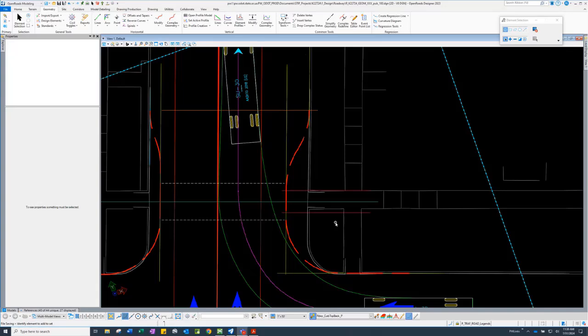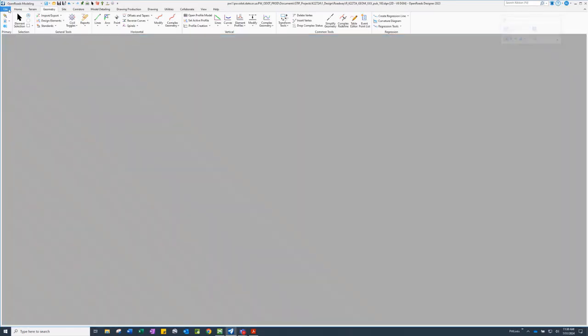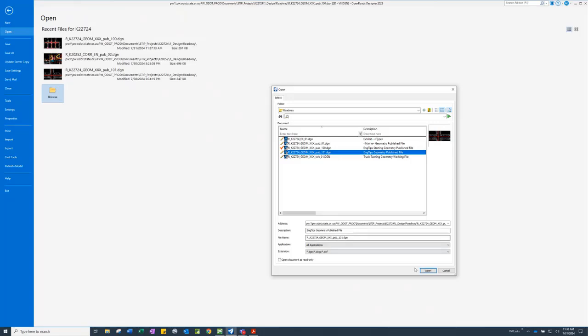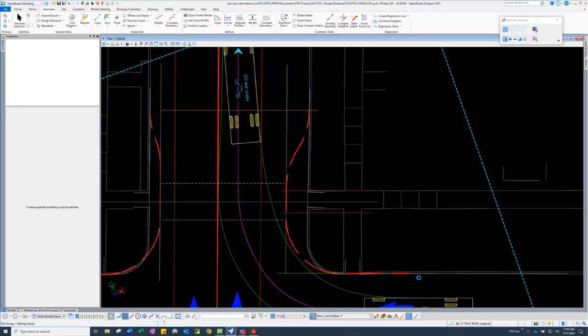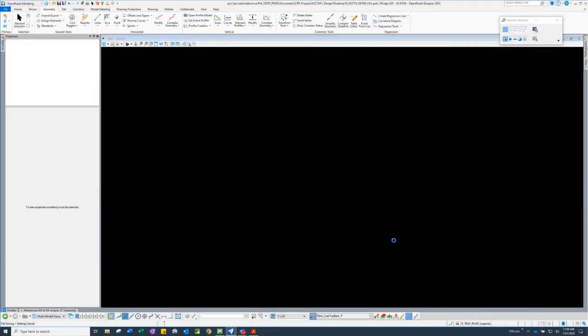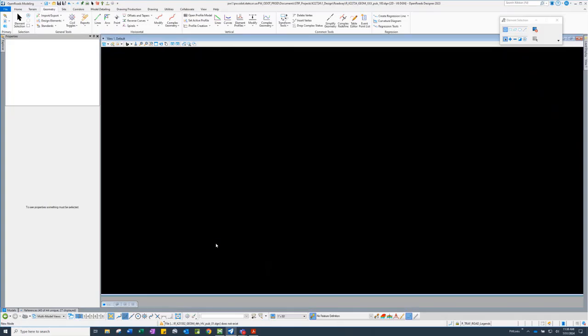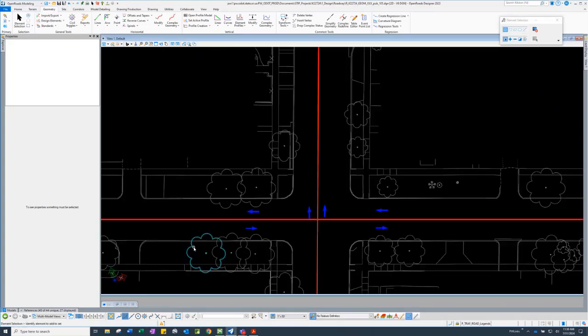Could you demo that really quick? Changing files. Would you mind? Let me switch a file. Yeah, file browse. And when you hit browse, it'll open up the ProjectWise Open dialog. Select a different file, and watch where the element selection tool is. Oh, right in the middle. Okay, you're going to check in the previous file. It automatically checks out the new file.